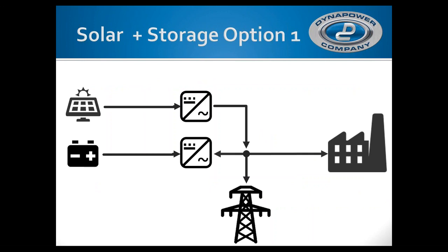So you've got a nice system that's operating. There's no problem with your PV inverter, but there's an interest in resiliency. So what do you do? Do you simply tack on the batteries with their own battery inverter, tie that into the system as presented here, or alternatively, do you rip out, in effect, the PV inverter and have a single inverter doing the job, carrying both the PV as well as the batteries? I'm going to present these as option 1 and option 2. No value judgments there with how they're presented, but we'll talk through some of the issues, and when we get to Dan's part of the presentation, we'll look at some of the projects where these different options have actually been implemented.